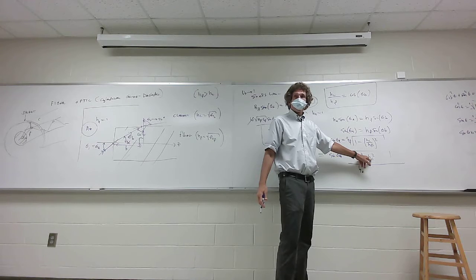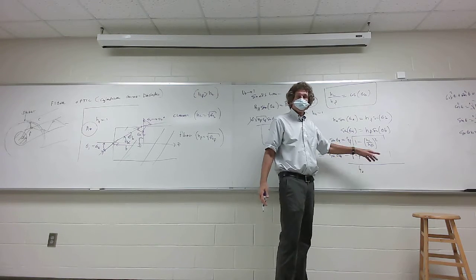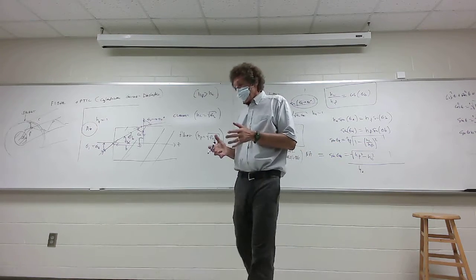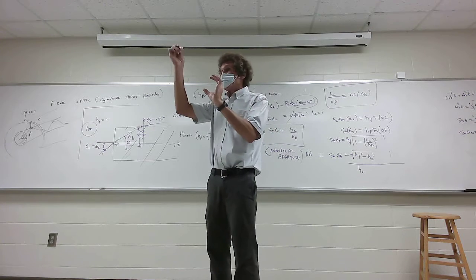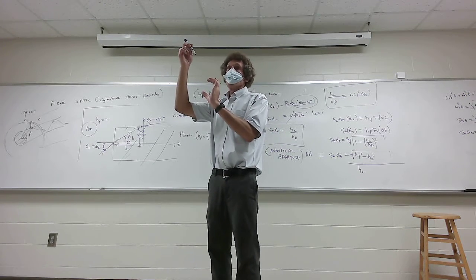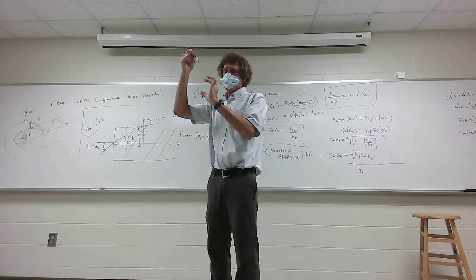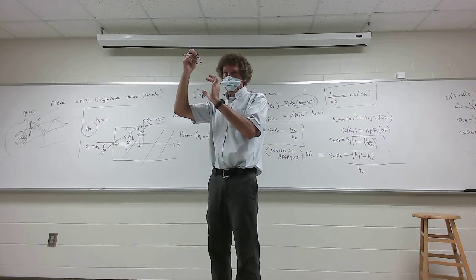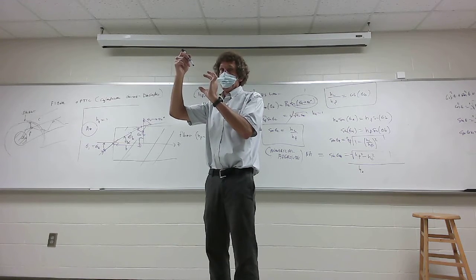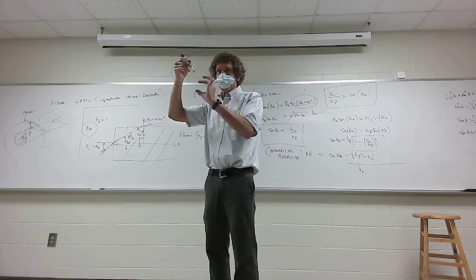When you talk about fiber optics, remember, it's going to be silicon dioxide and then something outside with some doping on it to change the index of refraction at the wavelength. All right? Now this is real important. All that stuff has to have the same thermal expansion coefficient.